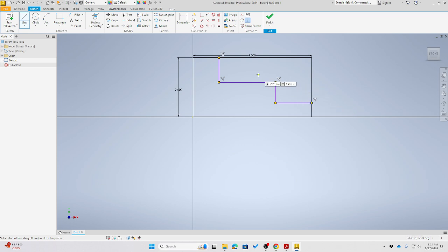This is my sketch, right? As you see, through the drawing I already defined it as perpendicular. But if in your sketch you're not able to see the perpendicular, you need to use this constraint. So let me go and do that.